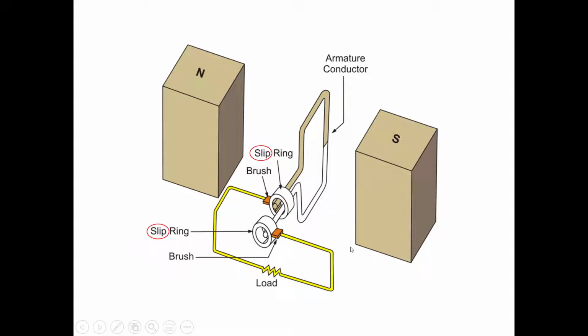Okay. The next thing they talk about in your module is the generation of this AC sine wave again, where we are running parallel with the magnetic lines of force. We would think that these magnetic lines of force are going north to south, so we have all these lines going across here. When we're parallel with them, or not cutting them, we're not going to be inducing any voltage into that wire, and that would be at our position at 0 degrees.